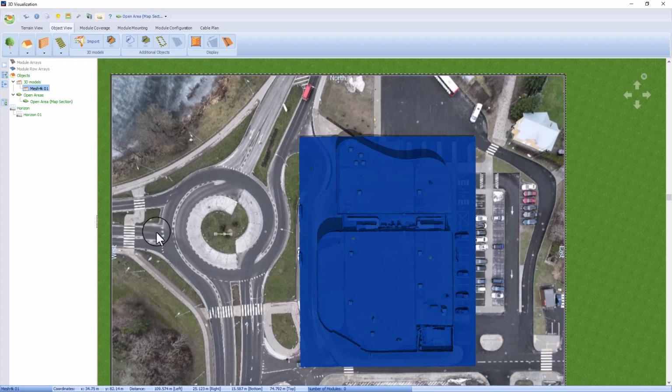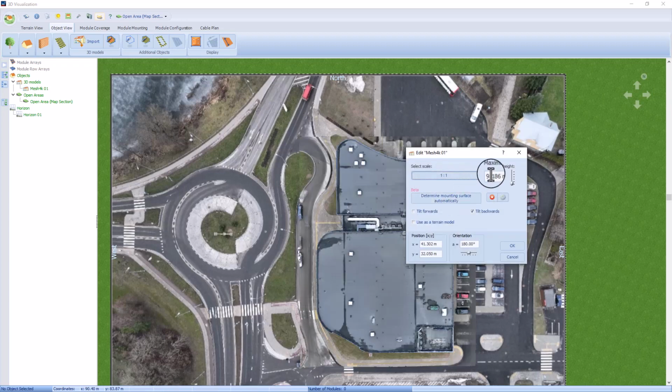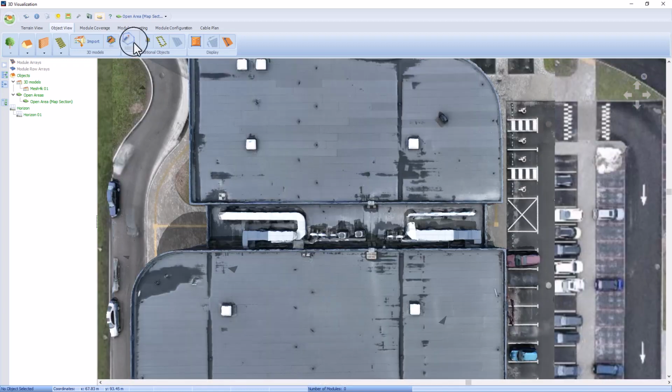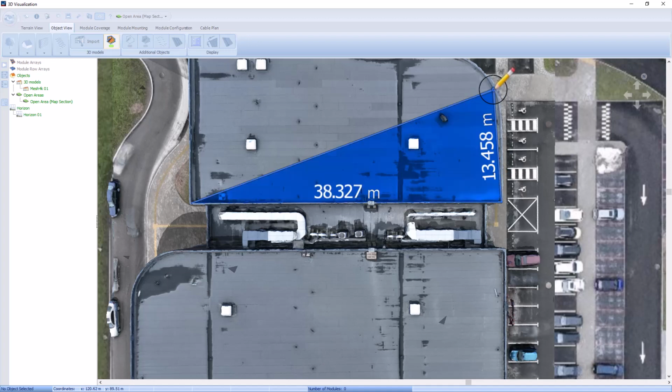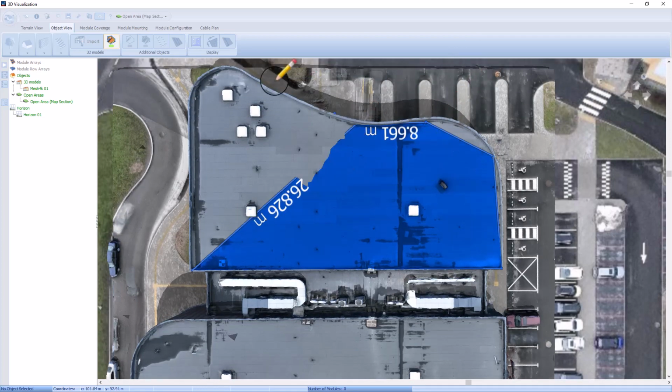There is an adjustment to the scale effectively. If you right-click and edit, you'll see you can adjust the maximum height. That is your scale adjuster. We're not going to adjust it in this case. But we can also use that orange colored polygon line to draw a line, 2 points, and it will show the measurement again, this time on the mesh. Again, you can decide whether to reset your scale, but we're going to carry on, and we're going to click around this part of the roof to create a mounting surface.